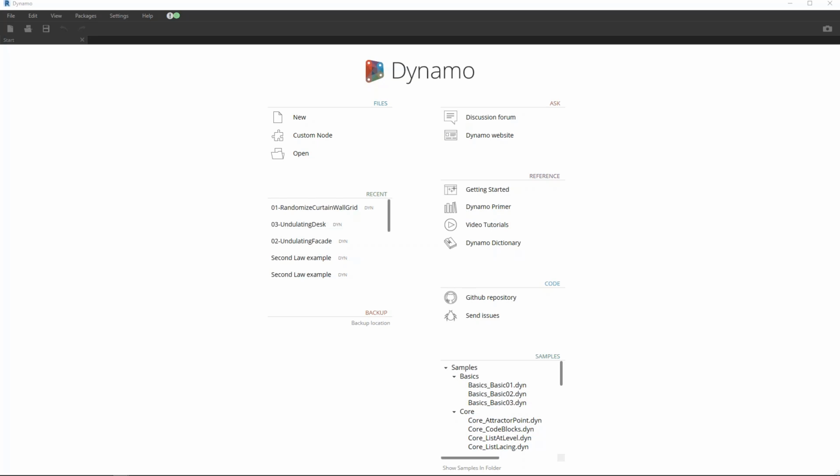Yeah, I've developed a couple of routines that will push the room number into the door tags so you don't have to manually type those in. I was going to be releasing that for a beta test. Another script will calculate the room occupancy load based on a function of space. So I'm going to be sending those out for beta testing. Awesome. Yeah, those are great uses for it for sure.